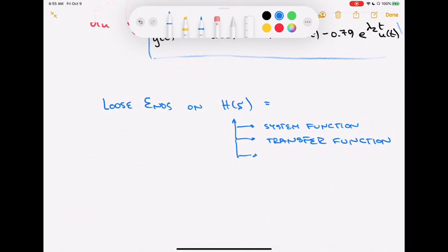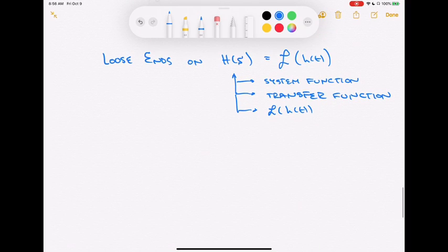And what was H(s)? It was the Laplace transform of the unit impulse response h(t). That's certainly one way of interpreting it. So we could think of this as the Laplace transform of h(t), right? We had also seen it in this sort of context as well. We know that it was something like, if I took an e^(st) into my system, right, out pops e^(st) times that H(s), right?